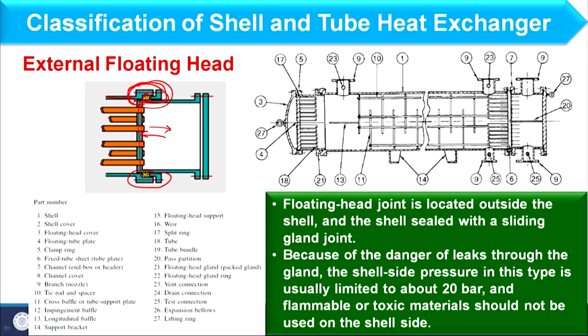okay. So, here I am putting one sealing, and the complete bundle can have thermal differential accommodation, right. It can be expanded or it can be contracted depending upon the temperature. Now, what is the problem? If I consider the movement like this, okay, and this section will slide over here, right. Now, if this section moves this way, then what will happen? If this section comes over here, then fluid can get out from this, okay. So, the limitation is, though the external floating head heat exchanger reduces the clearance significantly, it can leak the liquid. So, leakage is the problem in this type of exchanger, okay.